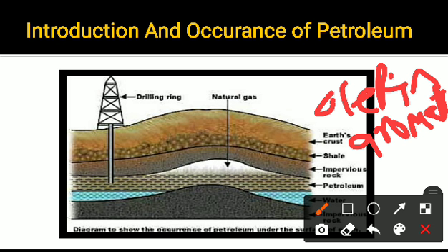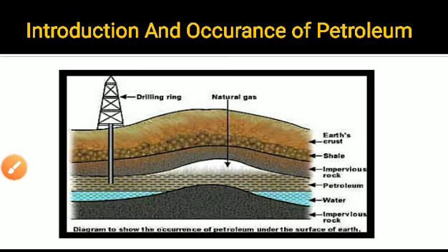Here the oil refineries produce olefins and aromatics by fluid catalytic cracking of the petroleum fraction. The chemical plant produces olefins by steam cracking of natural gas, and the aromatics are produced by catalytic reforming of naphtha. Here, let us learn some occurrence of the petroleum.